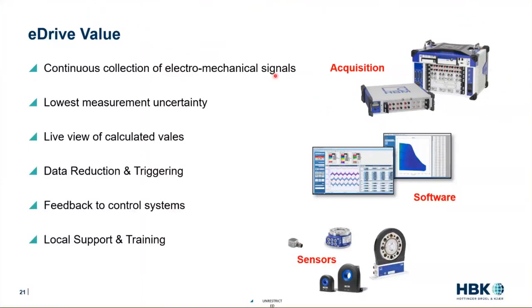So you can time align your temperatures, your CAN bus, your voltage, your current, your vibration, all in one place, your torque, your speed, so that you can understand how is my inverter affecting my torque ripple? How is my inverter affecting my temperature? And then note the changes between that.